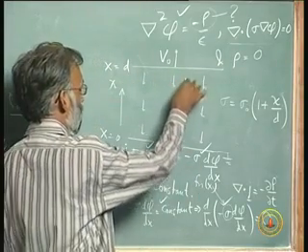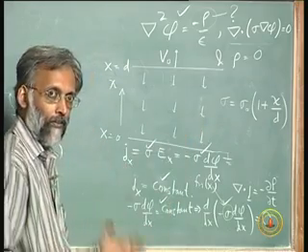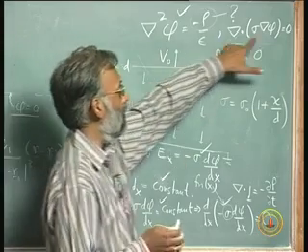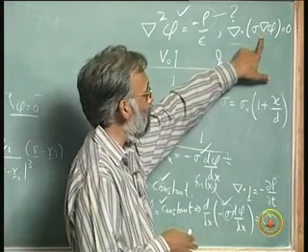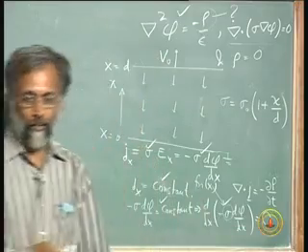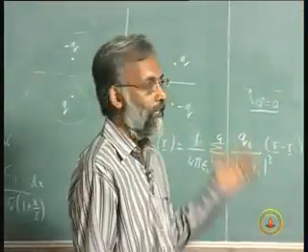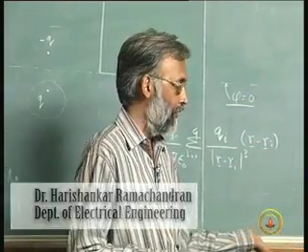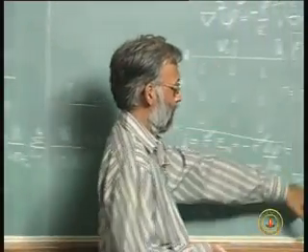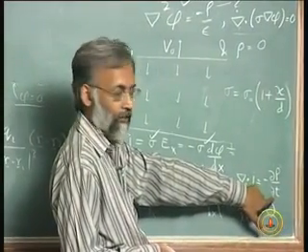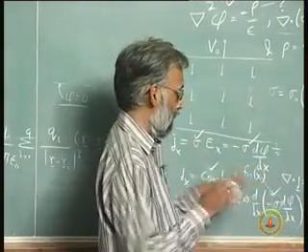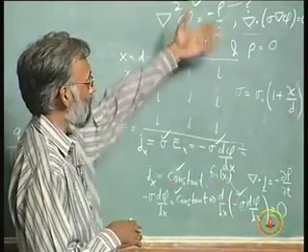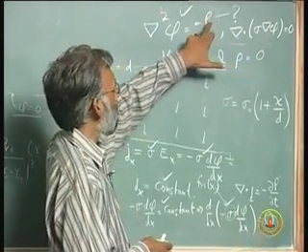So, the dielectric actually becomes charged, and over time that charge settles in every part of the dielectric to make sure that this equation is true. This is the equation that controls a leaky capacitor, because we cannot have current building up, that is not acceptable. But while it is building up, it is possible to have del rho/del t being non-zero, because charge is building up. Once it has finished building up, it must be true that J is constant, and if J is constant, it must be this equation that is true, and therefore there is charge present.